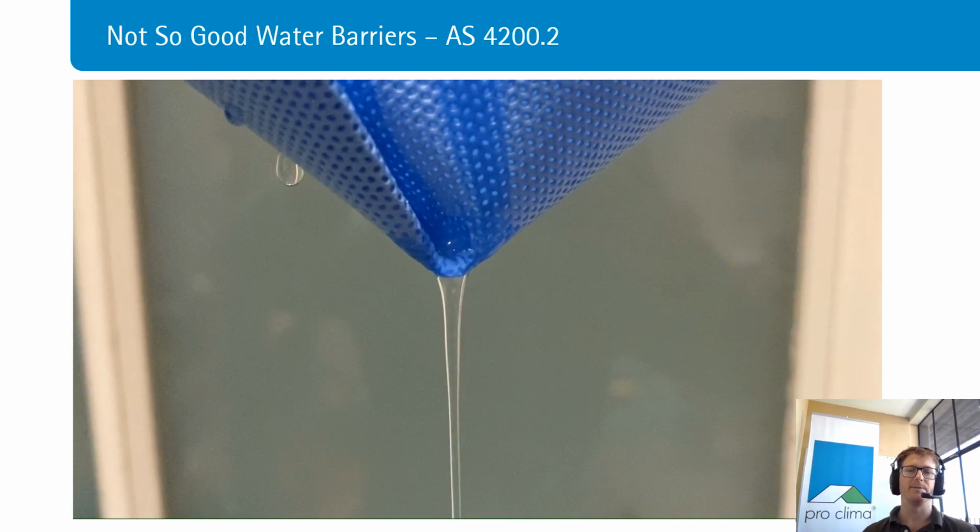So what can happen if weather resistive barrier membranes are just engineered to meet the 100 mil head of water is that if they come under any significant pressure when water is present, it could force water through the membrane itself. The other issue is that this type of membrane commonly, if it comes in contact with any materials or chemicals that can act as a surfactant, like oil, grease or tannins from timber, can lead to the water being able to pass through the pores of the membrane and not acting as a water barrier anymore.